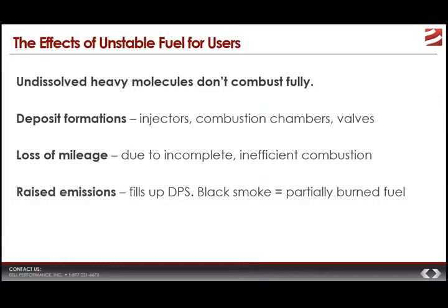You're also going to get raised emissions because they don't combust fully. You're going to get a higher incidence of black smoke. If the diesel engine has a DPF system, a diesel particulate filter system, that's going to get filled up faster, which causes you to have to service it or regenerate it more often.